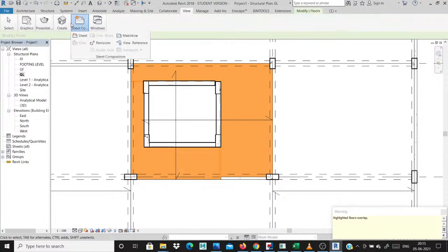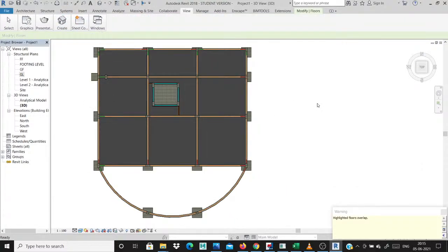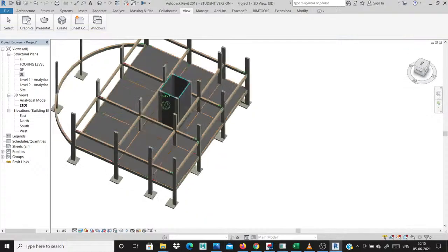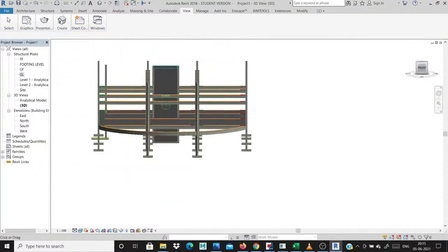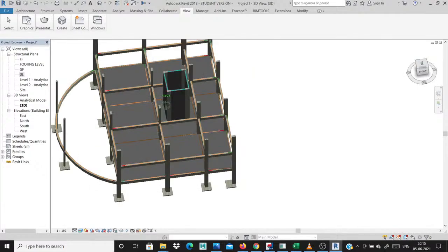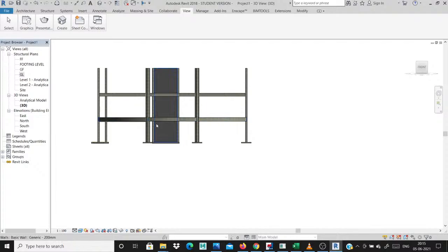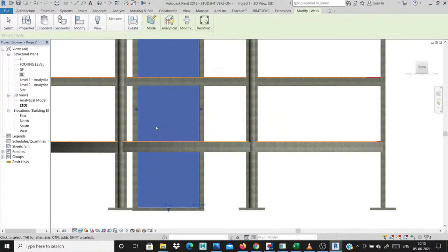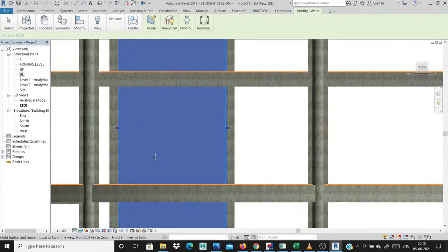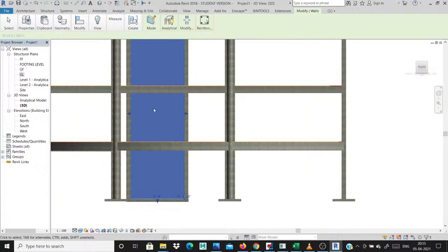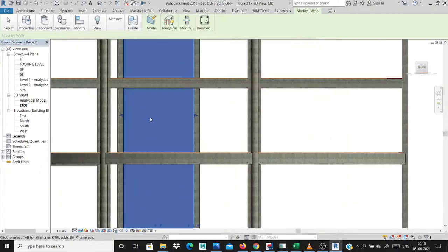So okay, then see this, automatically it creates the floor. Then there is a shear wall, so these center portions are openings. Okay, then there's a lift area. Then how to cut your walls in this first floor? This is the ground floor, there is no cutting portion. This is the opening for my lift area in this ground floor also. How to open for this shear wall?